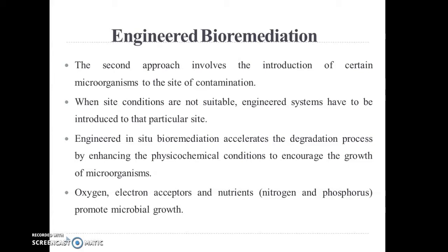Engineered in situ bioremediation accelerates the degradation process. It will increase the pace of bioremediation by enhancing the physicochemical condition to encourage the growth of microorganisms. Oxygen, electron acceptors and nutrients, that is nitrogen and phosphorus, promote microbial growth.